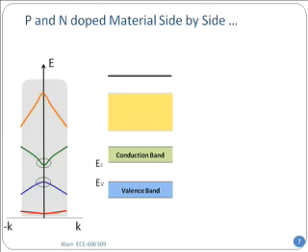Now, by the way, the straight black line on the top of this we'll call the vacuum level. Vacuum level means that if an electron can go up that far, then it will leave the semiconductor, right? Photoelectric effect, do you remember? Shine light on it, the electron jumps up, and if it has enough energy, then it gets out of that material. So that black line is called a vacuum level, because the electron will then be free from the semiconductor and it can go outside.